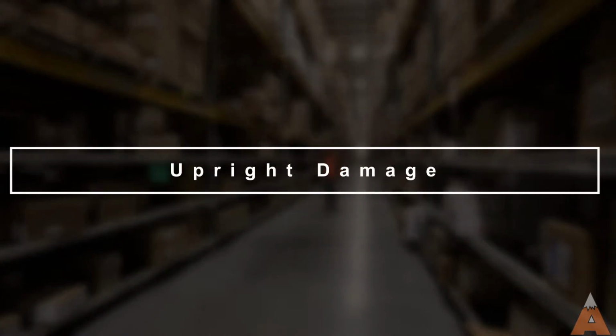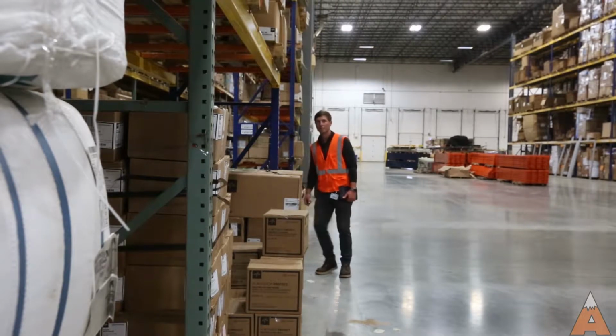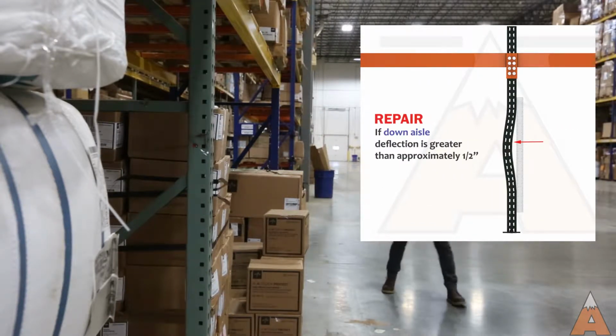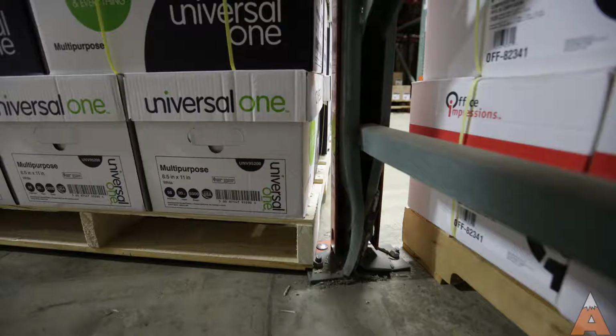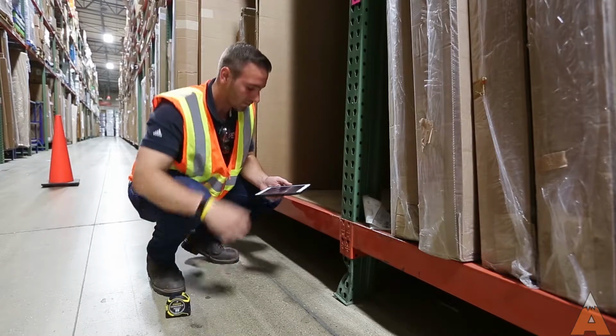When recording upright damage, be sure to note any deflection greater than a ½ inch from front to back and down aisle. Indicate if the steel is torn and where the damage resides within the upright. If there is a separation between the column and seismic backer, note that it is damaged and check to see if the frame is plumb front to back and side to side.